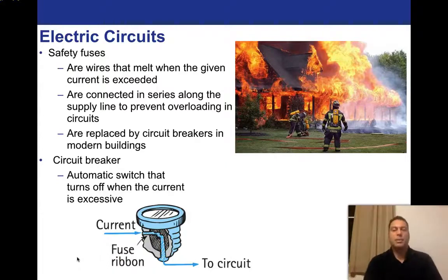The main things that you want to make sure you pull out of this is Ohm's law, the relationship between these things, and understand what a resistor is. A resistor is really just a spot on a circuit where we use the electrical current to do work or to produce power. And if you understand that current equals voltage, which is given in volts, over resistance, which is given in ohms, you can do a lot of really powerful calculations with that. And you'll be doing some of that in the homework sets.